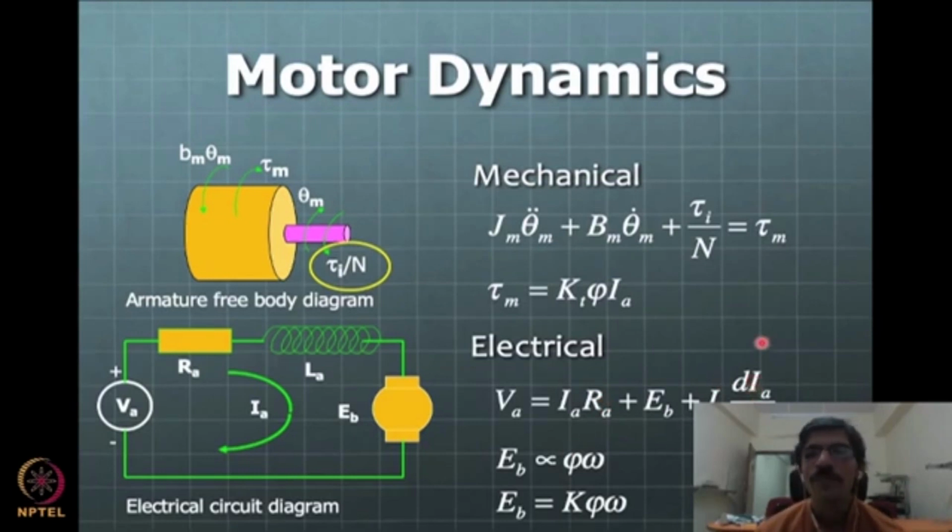So there are two things. Although this current may be changing so fast, the motor winding inductance is very, very low as compared to this back EMF or these voltages that are given here, other quantities. So this term gets neglected in the actual representation practically. So with this term there or not there, you can try to see what the motor model equations look like, and then you can take some example and simulate also.